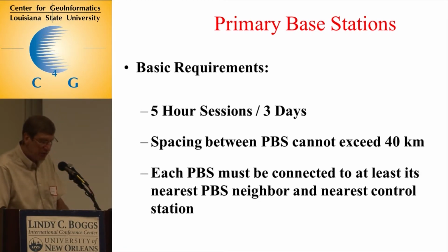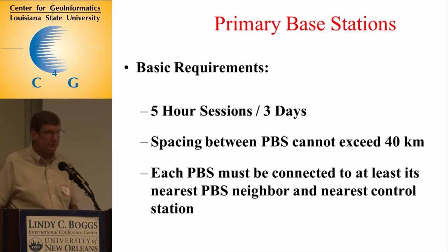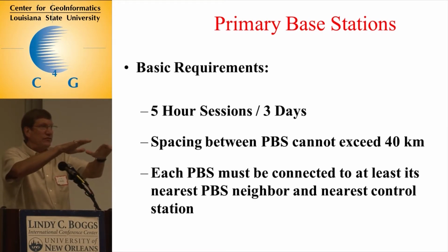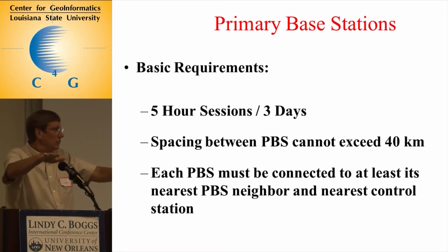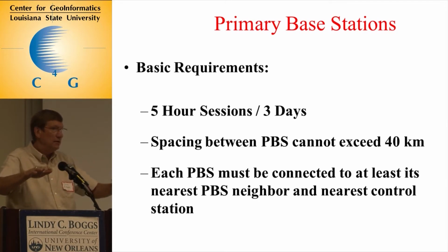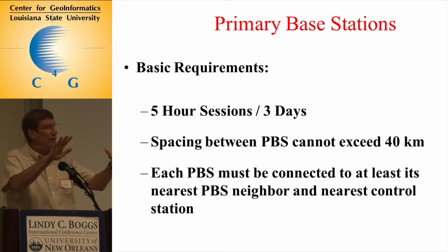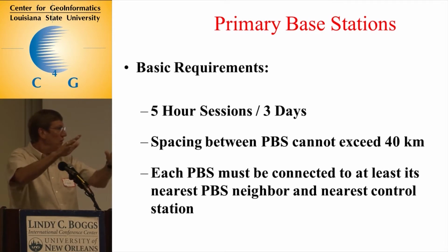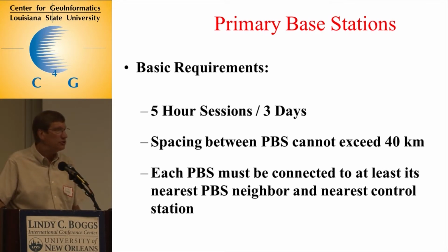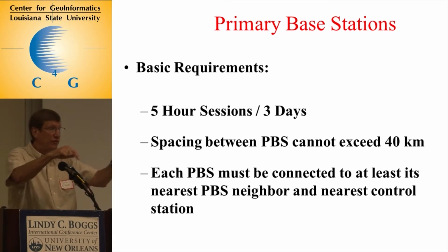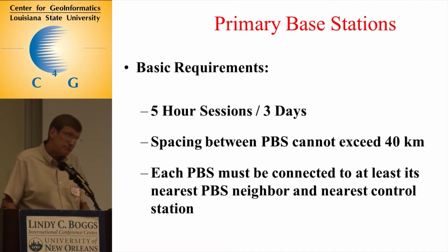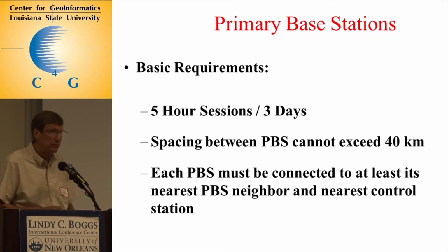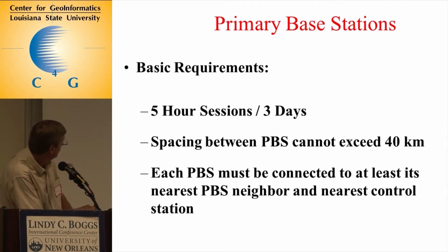Because remember, when we're done building this network, we're going to have these stations across the country, wherever you are, or your state. And you've got to make sure you don't have any kind of tilt to it, any kind of long wavelength error to it. You've got to make sure that the one station next to the other is really good to a few centimeters, because you're going to want to fill in between it. The only way, without taking real long sessions, the only way to do it, the way I found at least, was doing it this way.